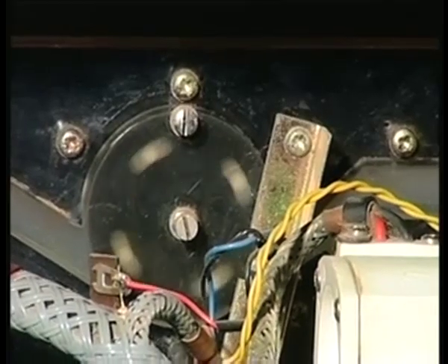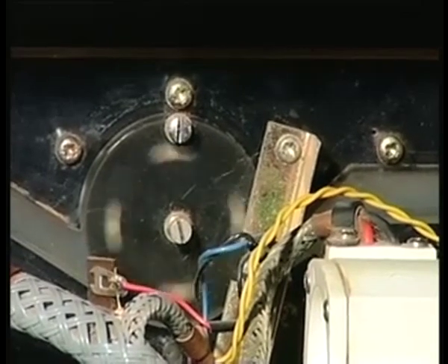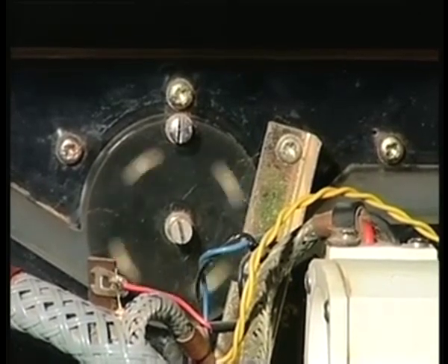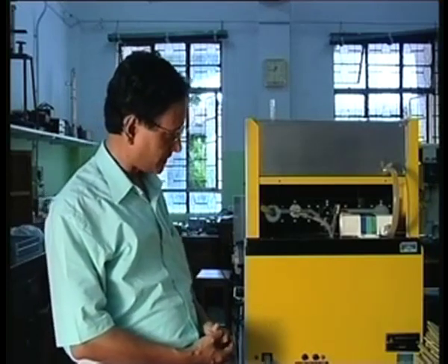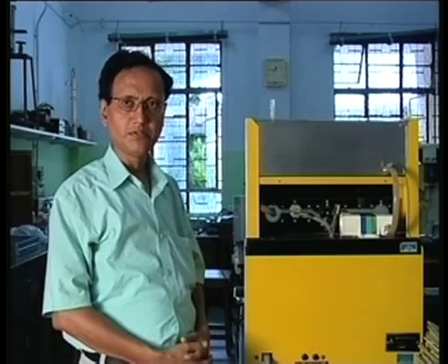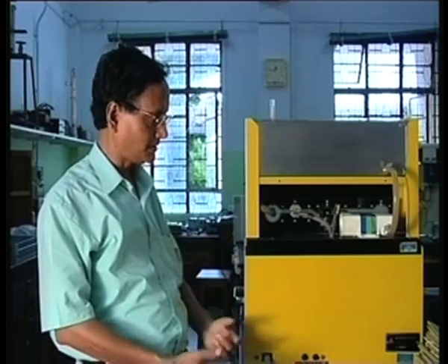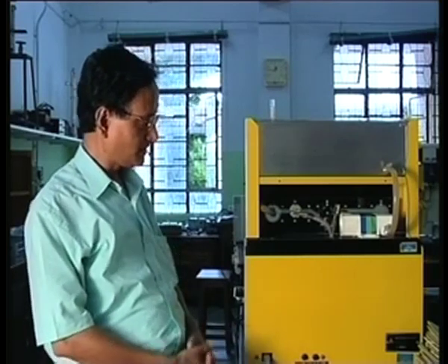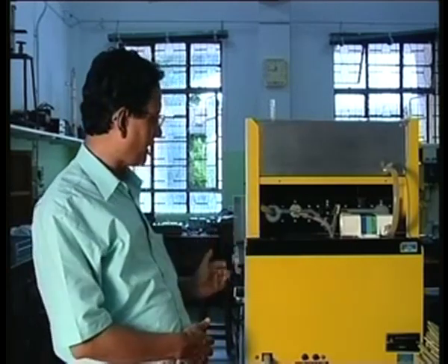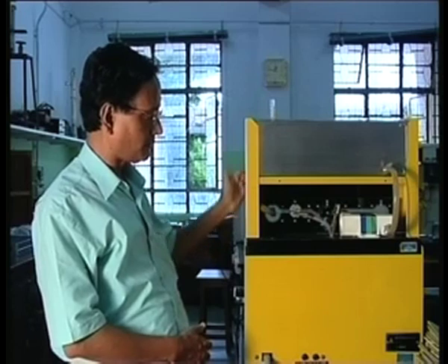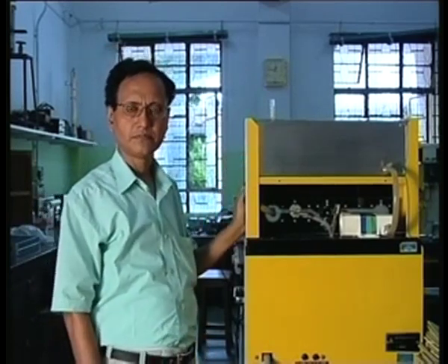You will get an output that can be counted for 60 minutes, so that you can get the flow, because if you know the flow pipe diameters and all those things, you can immediately tell how much the flow rate is in a minute. So this will give you a direct electrical output that can be processed and easily interfaced with the computer. So this gives the glimpses of the different flow sensors in the system. And this can be calibrated with the rotameter in the front side, which I showed at the beginning of this lecture.